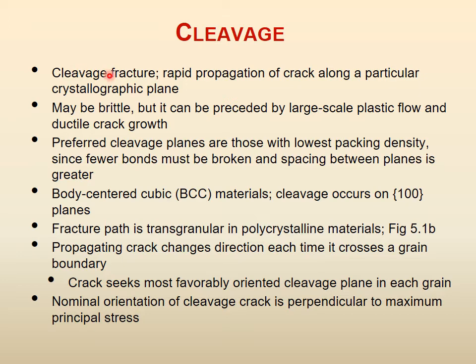So cleavage fracture is rapid propagation of a crack along a particular crystallographic plane. Rapid, right? Not like crack growth. It may be brittle, right? Cleavage is basically brittle in nature, but it can be preceded by large scale plastic flow and ductile crack growth. So this is right.